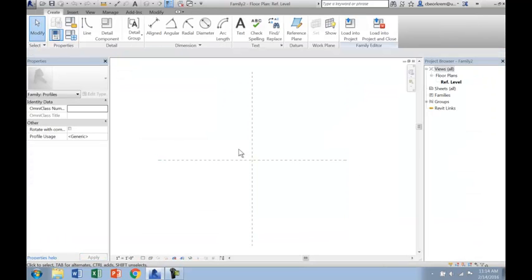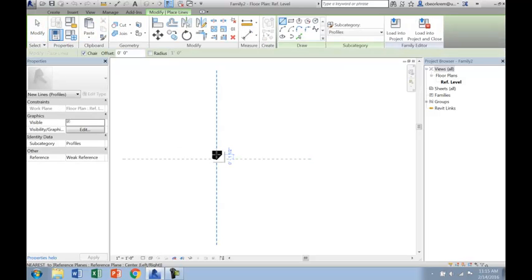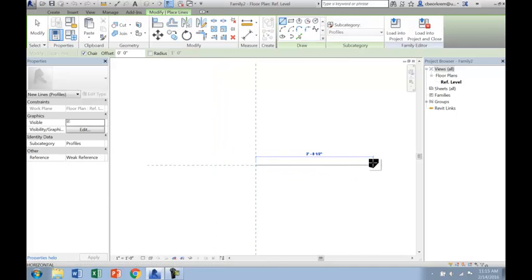And all it brings up is just two reference lines. Those reference lines are simply going to provide us the orientation we need for extruding this solar fin. I'm going to start off just drawing some lines. All we're doing is drawing a profile here. So I'm just going to give a center line that we can reference off of. Let's make the profile, say, 14 inches deep.